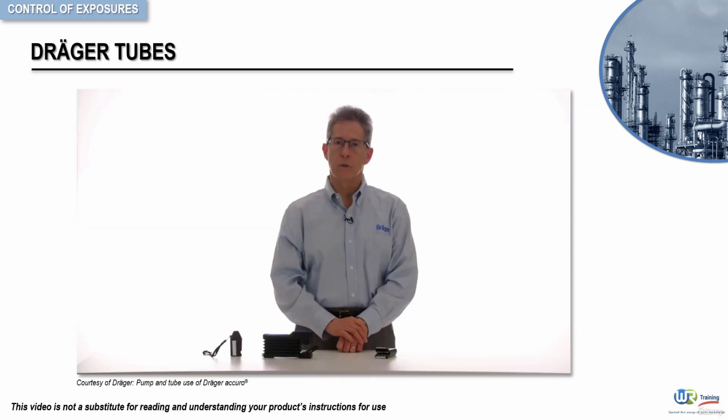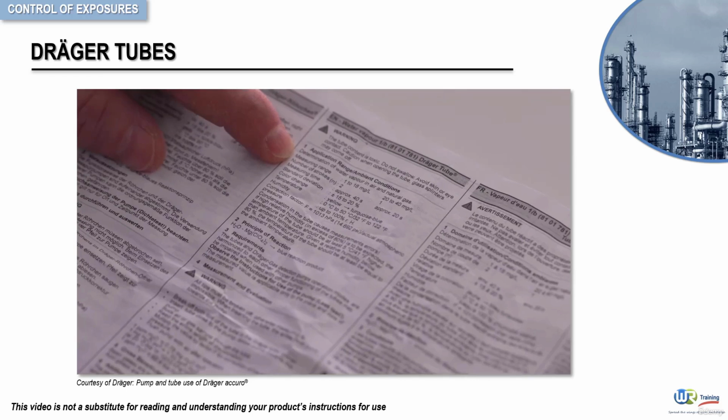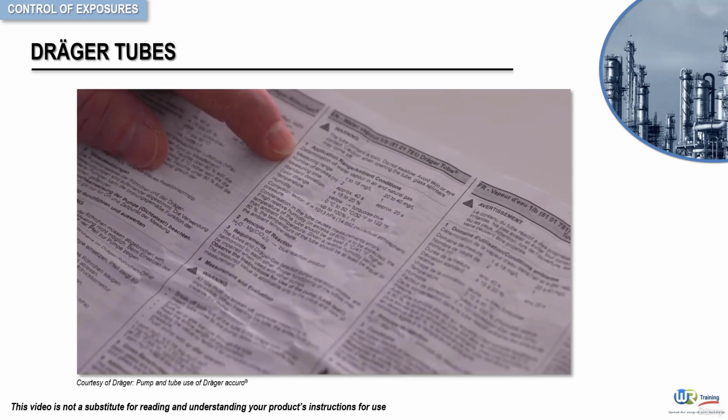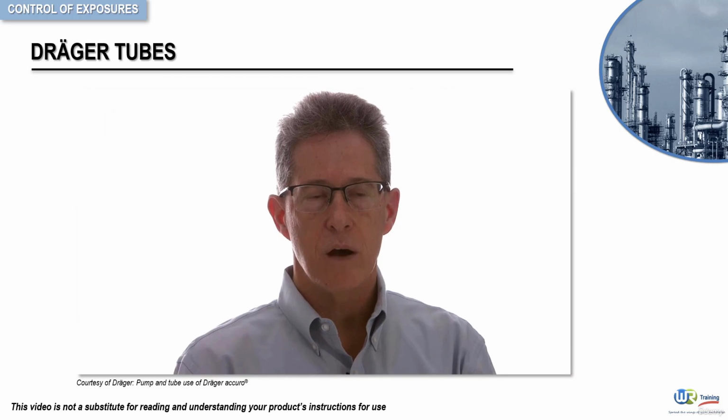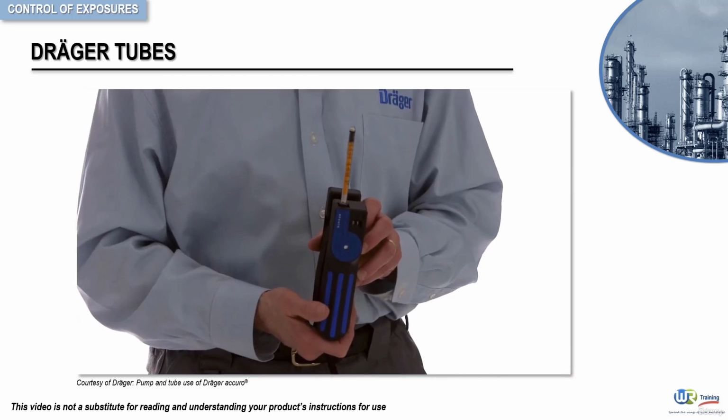Take the required number of strokes according to the instruction sheet in the package. This tube has a high range scale based on n equal 1 stroke and a low range based on n equal 2 strokes. This means that if the discoloration reaches the high range with 1 stroke, read the tube, but if not, take 1 additional stroke and read the low range scale.